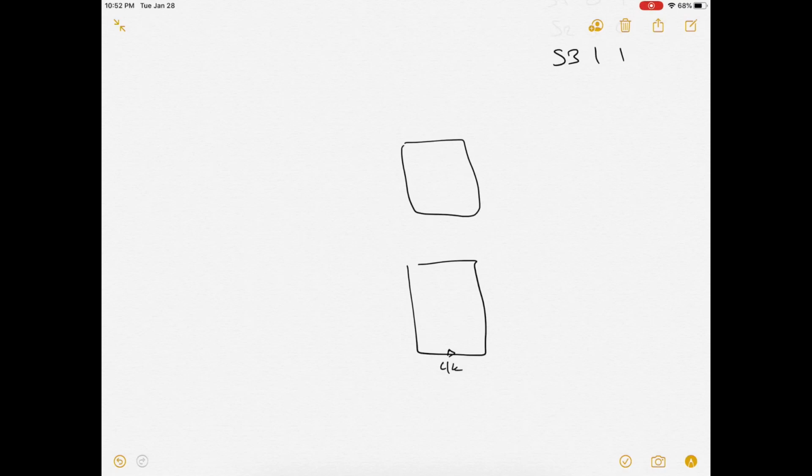Each one will have a clock, and this is the input, and this is the output. So this output is basically what state we are in right now. This will represent the current state, which is represented by Q1 and Q0. So if we see here on these wires 0 here and 0 here, it means that right now we are in state S0. If we see 1 1, it means we are in state S3.